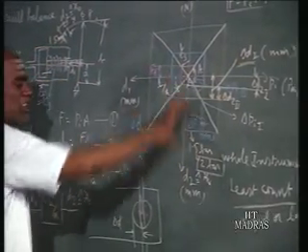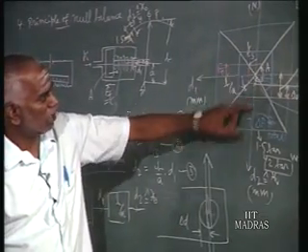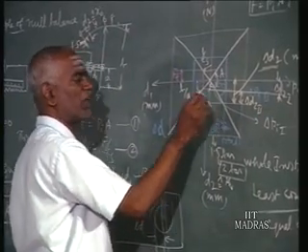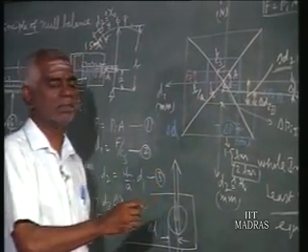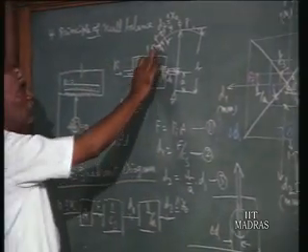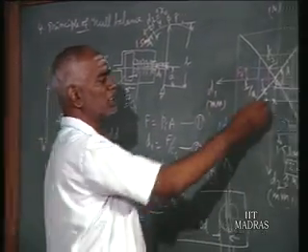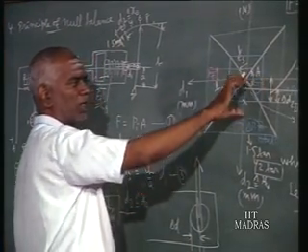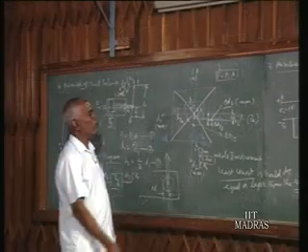You can read it because it is a scale. Output scale is plotted here. So for this much output error, you can find the term in millimeters. If it is 1.5 or more than 1.5, fine. Suppose it is less than 1.5 mm, then the graduation is also going to be less than 1.5 mm, which is not permitted. So for the same input error, the corresponding output displacement should be more. How to do it?